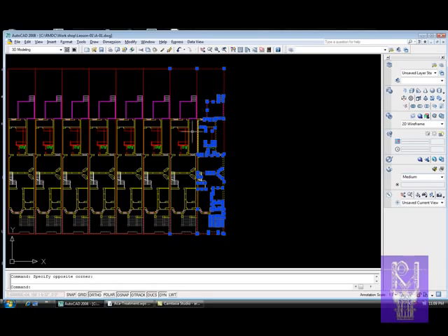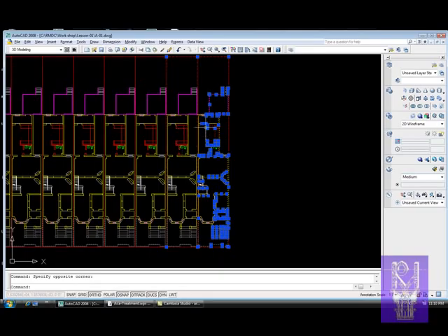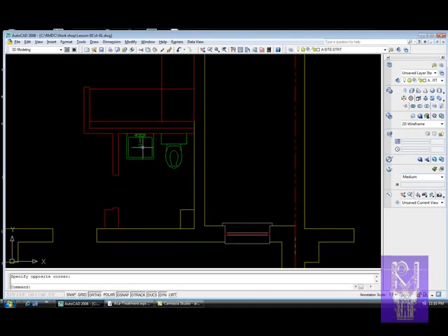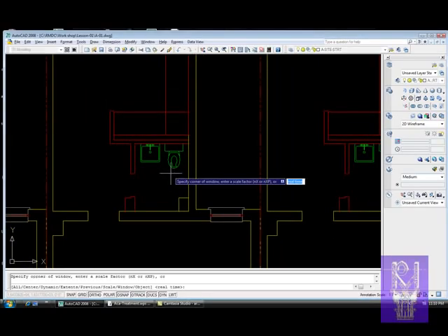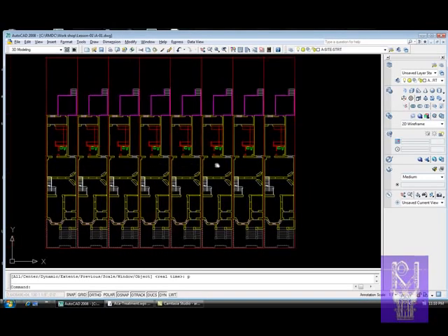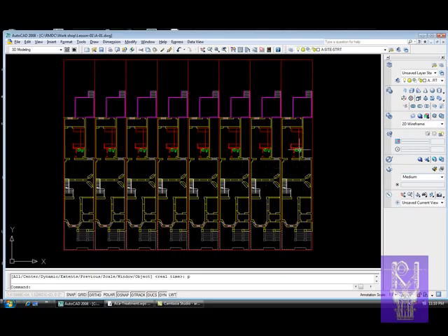up, then we would have to make a block out of this one system and then copy it, and then we can mass produce it across. Right now everything is individual, and it'll eat up a lot of memory. And if you had to make changes to an element in the unit, say for instance the toilet and sink had to be rotated to this wall on all of these, the best way to handle that